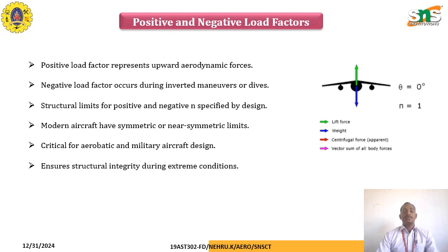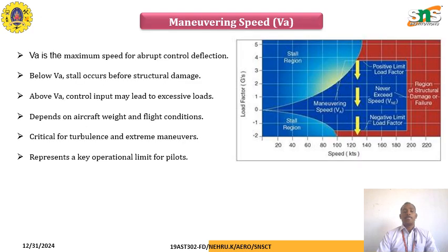Modern aircraft have symmetric or nearly symmetric limits for both positive and negative load factor. This is critical for aerobatic and military aircraft, and is a major design criterion, which ensures structural integrity during extreme flight conditions.